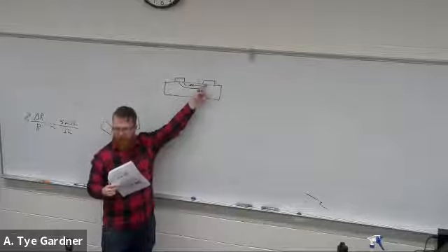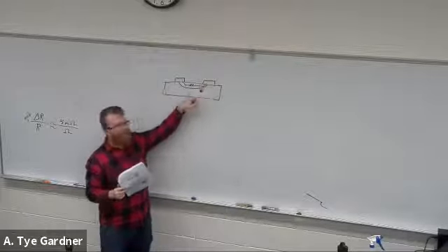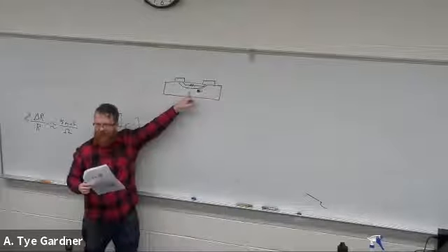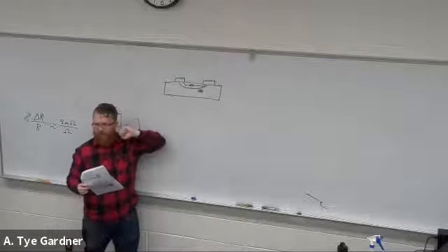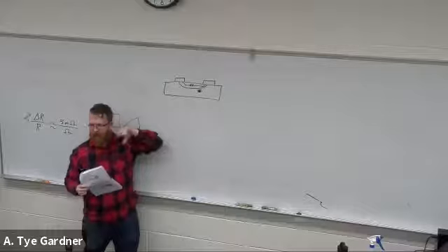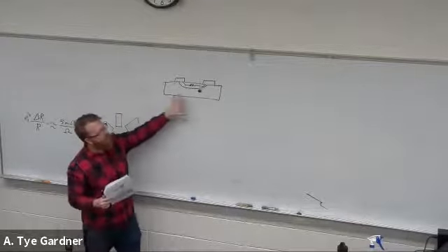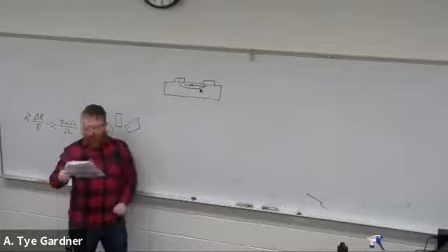If you have power supply noise, for example, or reference noise, it's very problematic because semiconductors are nonlinear, right? Unless they're very carefully designed, it's going to have a nonlinear response to a change in voltage across the semiconductor. So we want to stay in about the same area and measure only that strain.